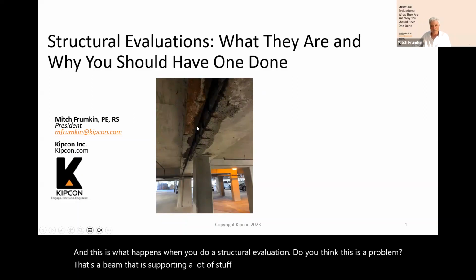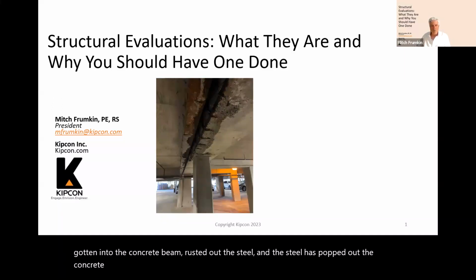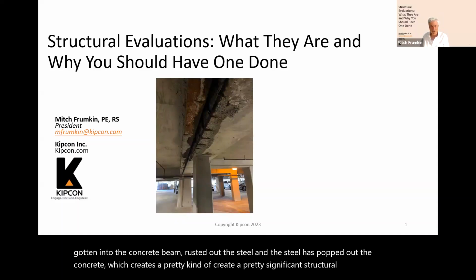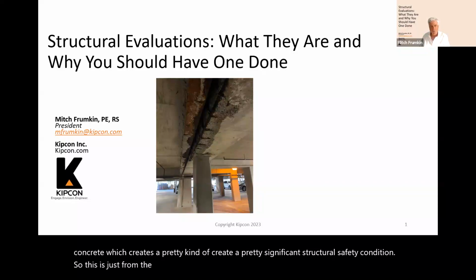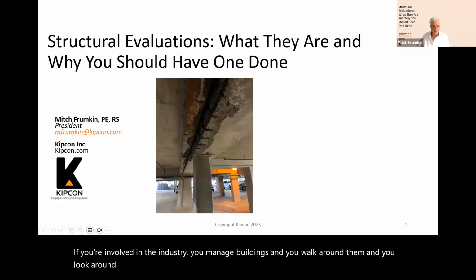You can see that the water's gotten into the concrete beam, rusted out the steel, and the steel has popped out the concrete, which can create a pretty significant structural safety condition. So this is just from last week. I will tell you that I see this a lot. If you're involved in the industry and you manage buildings and you walk around them and look around, you'll see what I'm talking about.